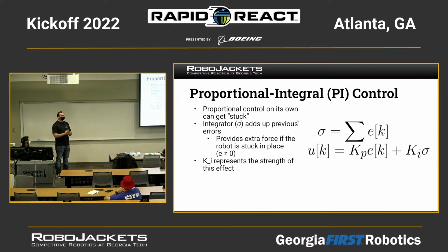The next thing we have is a PI controller. So we had before the PD worked pretty well for the application we were talking about. But if you were trying to stabilize in velocity, you would have a little issues with the PD controller. So what a PI controller really is for is steady state error. If we ran a P controller, we'd eventually cap out at some point, and usually that's not exactly where your set point is. So the integral allows you to do the last gap there.